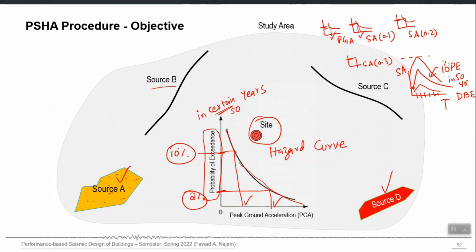So one more thing is that in constructing that one particular line, the spectrum of the future earthquake, you considered one fixed definition of hazard in picking the number from all hazard curves for one site. This spectrum is called UHS, Uniform Hazard Spectrum. So the response spectrum by default is UHS, right. Why uniform hazard?